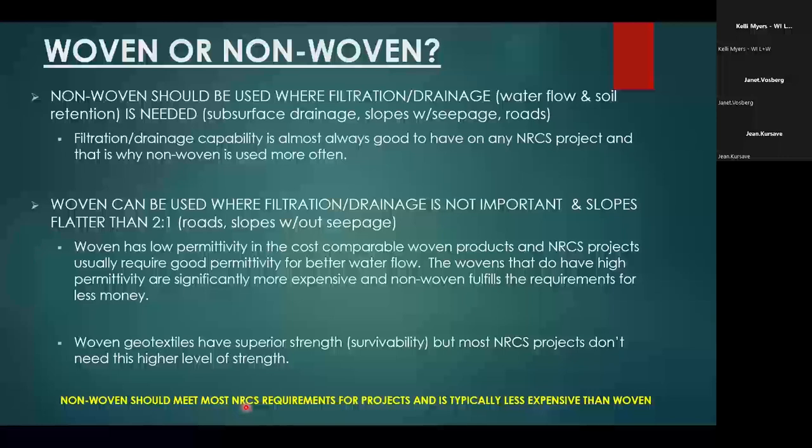Wovens are slipperier, so we don't want to be using them on slopes necessarily unless it's a really steep slope and we're using it basically as the wall. There's applications for woven in that case.